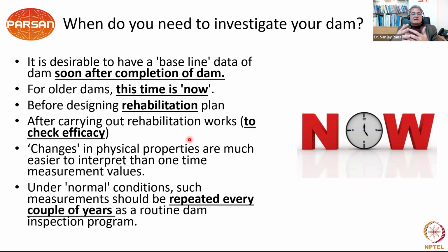And once you do multiple lines, you can actually draw the path of seepage in the canal also. The next question is, when do you need to investigate your dam? So the fact is that it is desirable to have baseline data of the dam soon after completion of the dam. Just like when we turn 40, the doctor generally advises us to go for an ECG. And he says that this will work as your baseline ECG, and in future we can always keep comparing with this.